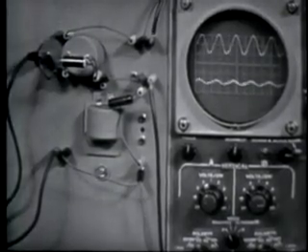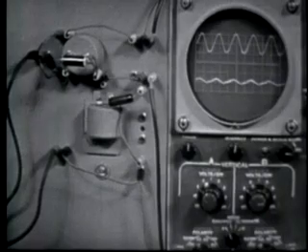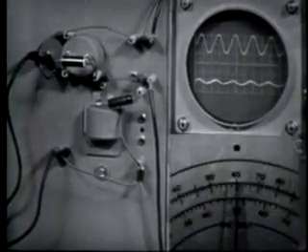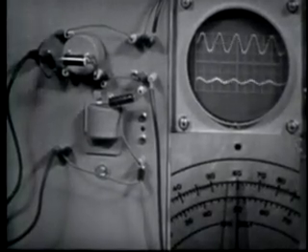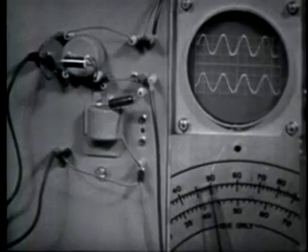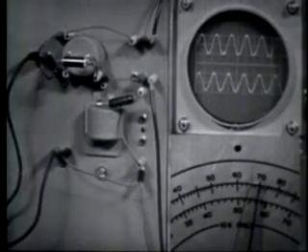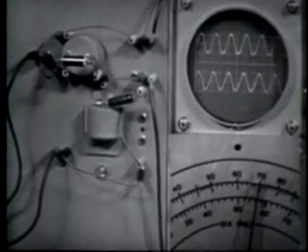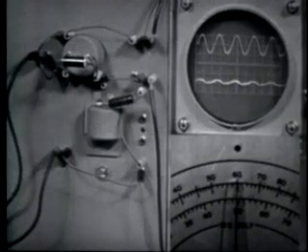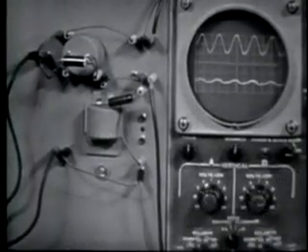Now we've said that the T and pi section filters provide improved filtering action over the simple L section. What do we mean by improved filtering action? Just this. This L section band reject filter rejects a band of frequencies from about 500 hertz up to about 700 hertz. Now since the specific frequency we want to reject is 600 hertz, this circuit is not too precise, is it? So let's make a T section from this basic L section and see if we can improve the